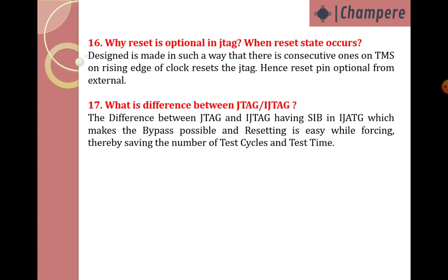So consecutively holding ones on the TMS on the rising edge automatically resets the JTAG. Hence, the reset pin is optional externally. That is one way to reset also.